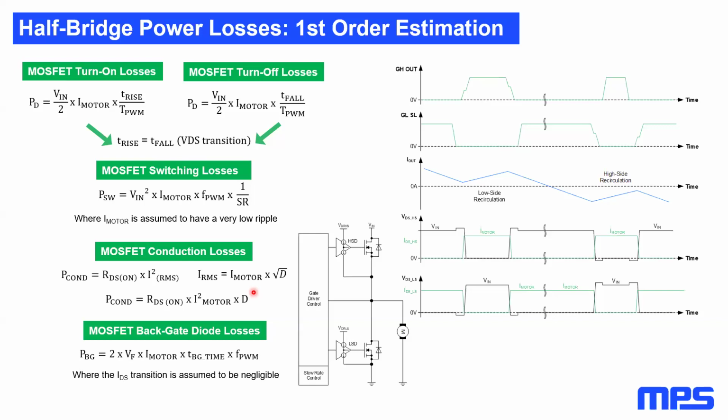Also, one thing that is not to be underestimated is that if you have a bridge, like a solder bridge or a 0 ohm resistor or a piece of metal that is supposed to, for example, be a loop for current measurement, these also have some resistance, which could be in the order of 1, 2, 3, or even 5 milliohms. So each and every path counts when you sum them up.